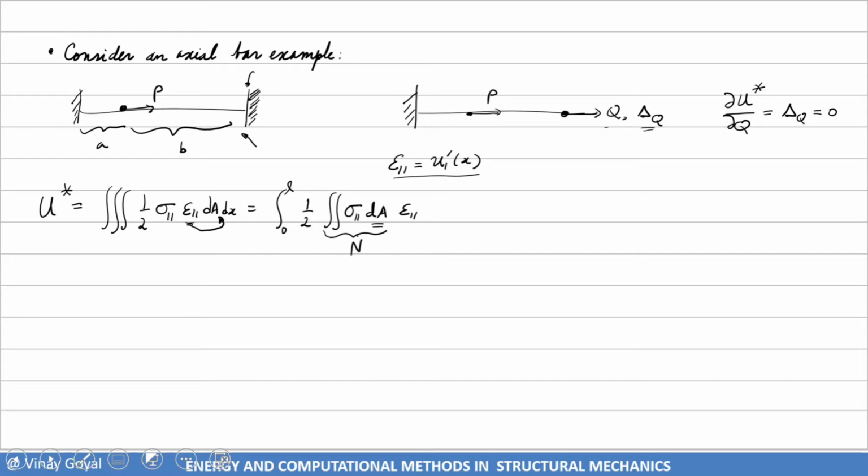That's the axial force. And if you forget anytime, you can look at the definition by looking at what this means. If I take the stress in a cross section and integrate the stress over the cross section, that's clearly an axial force that's causing the bar to stretch. So now I'm able to make the step and say, okay, well, this is 1/2 N epsilon 1 dx.